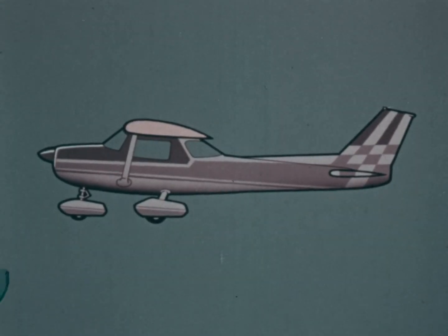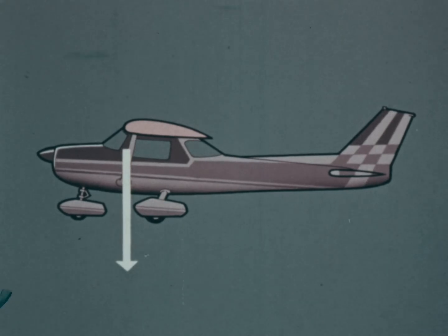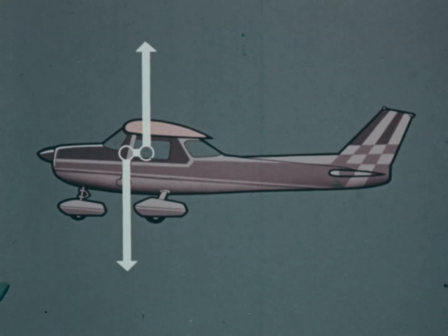The total weight of an airplane acts through a single point known as the center of gravity. The designer tries to put the center of gravity a little way ahead of the center of lift of the airplane, so as to give the pilot better control. This is compensated for by fixing the tailplane at a lower angle of incidence than that of the wings, so as to give it a download. But the loading of the airplane can change this relationship.